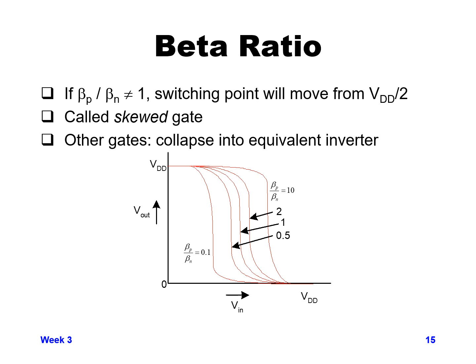But if your beta P to beta N ratio isn't equal to 1, basically we call this a skewed gate. So you can skew the gate to be higher skewed toward P or lower skewed toward P. So if your beta P to beta N ratio, your P is much larger than N, that's called a high skew gate. So your PMOS device is a lot larger, a lot stronger than your NMOS. And if your PMOS device is a lot smaller than your NMOS, that's called a low skew gate.